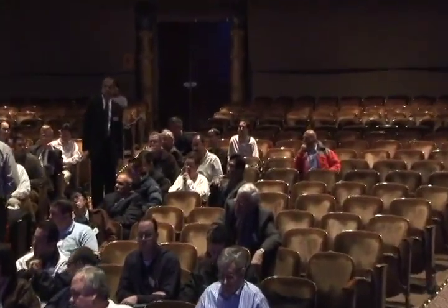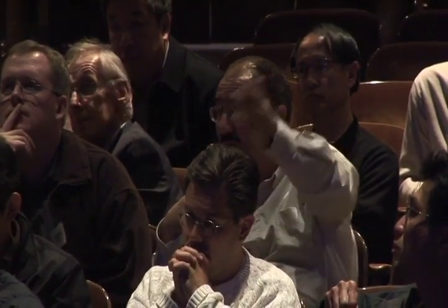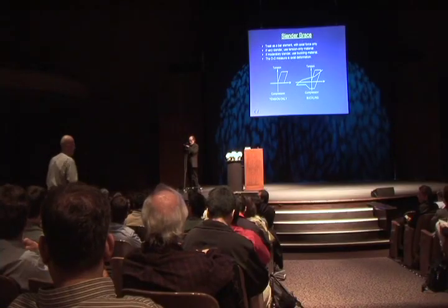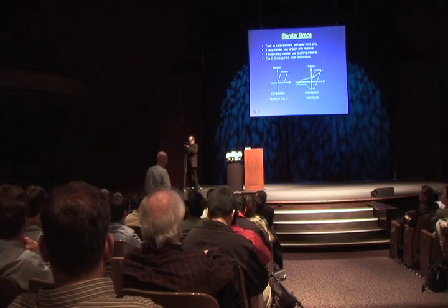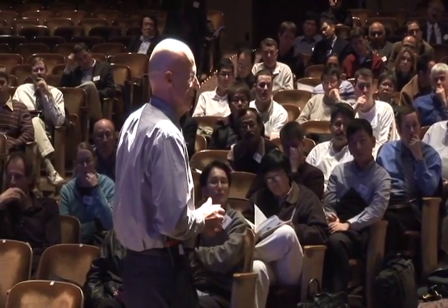We've used Drain-2D in the past to do something like that, and I don't know if the same input variables, like changing the stress-strain curve of the confined concrete, can be imported into... Yeah. So you say you've done it with Drain in the past? Yeah. Anything you've done with Drain, you can do with Perform. And Perform actually, to some extent, is based on Drain-3D, but it's Drain-3D on a heavy dose of steroids. It does way, way more. But anything you can do in Drain-3D, you can do in Perform.